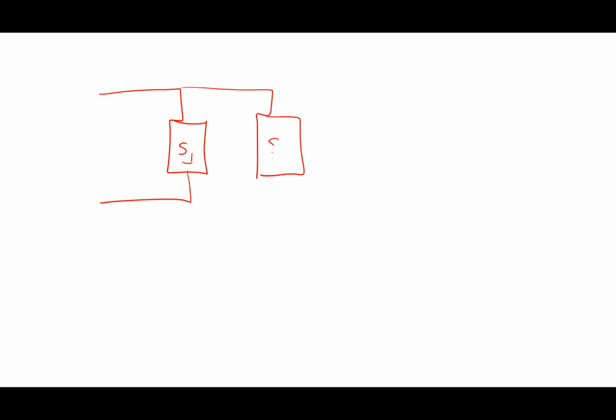All right. So one last thing here is I want to get the power factor of the combination to be unity. Maybe I'll talk a little bit more about why that is on Friday, but I've got the two loads in parallel with each other, S1 and S2. The total power delivered to those loads, I'll call it S, is equal to S1 plus S2.